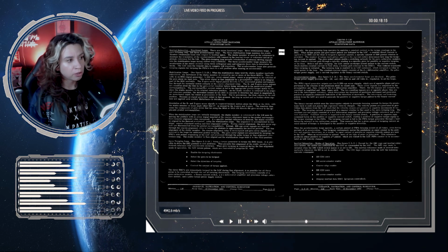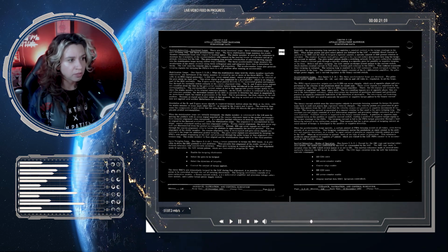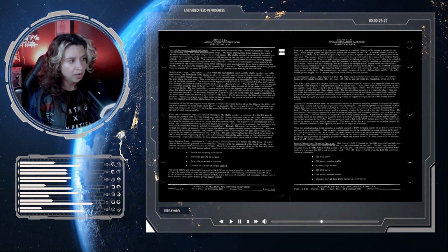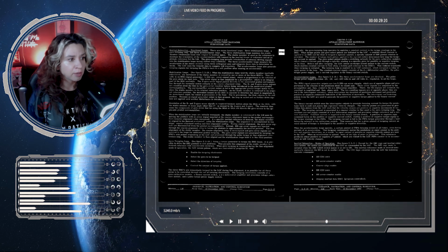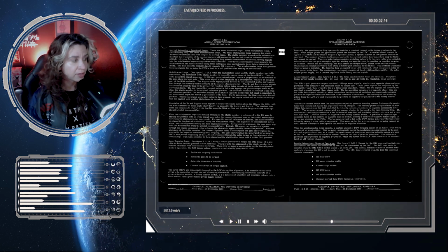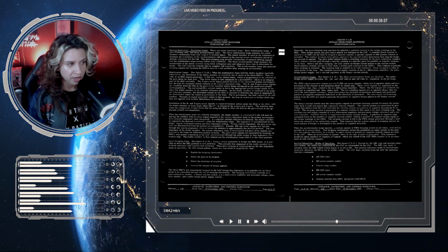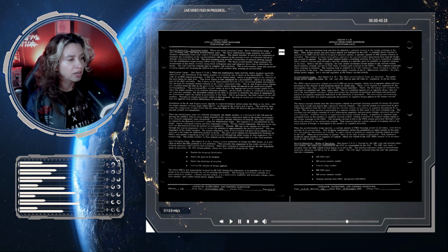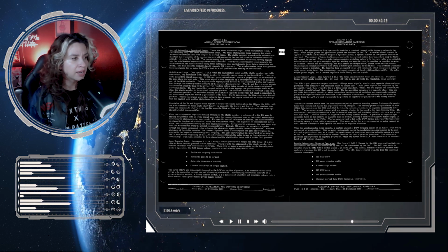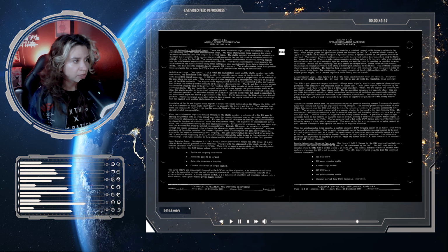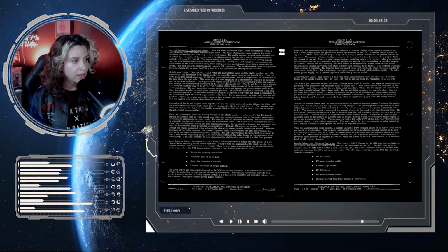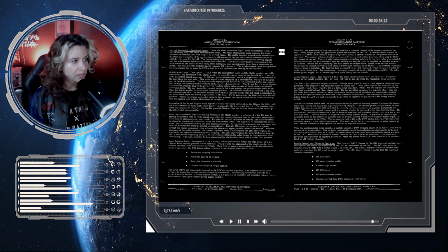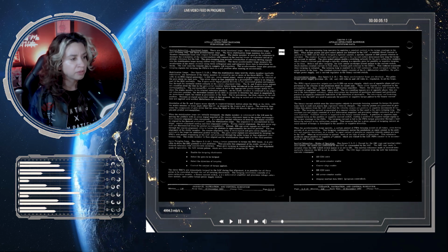When the stabilization loops are inertially energized, the stable member is referenced to the LM axis by driving the gimbals with an error signal inserted at the coarse alignment input to the gimbal servo amplifiers, with the coarse alignment relay energized. If a specified inertial reference is desired, the stable member is aligned to the desired orientation. Using the stabilization loops, the alignment is accomplished in 2 steps: coarse alignment mode and fine alignment mode. During coarse alignment, the gyro error signals are disconnected from the gimbal servo amplifiers.